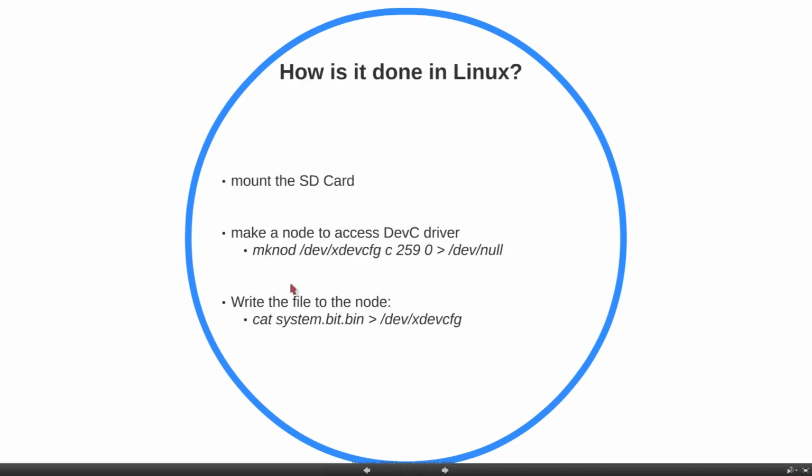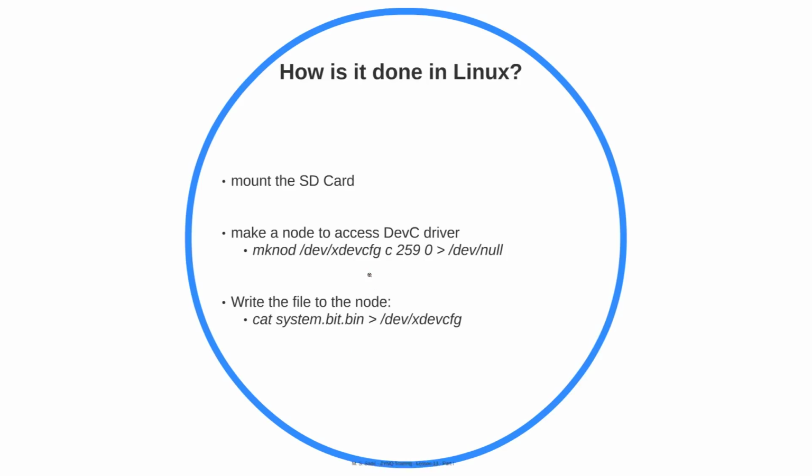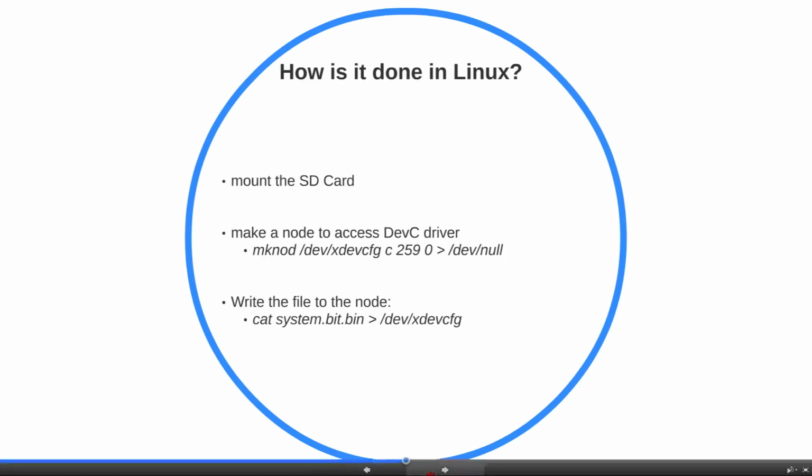But in standalone mode, the task of reading a file from the SD card and the task of initializing the PCAP and telling it to read the data from the DRAM and copy it to the PL all have to be handled by the application that you write, which is going to be executed on the ARM host.